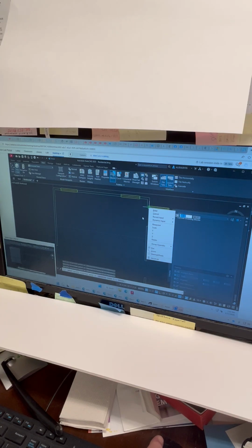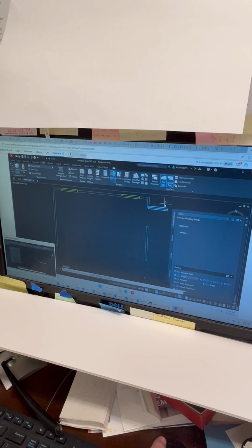Now look, auto placement, repeat placement, we've got another one. So go to the next opening. Same thing, rotation angle, except 0 as the default, just hit enter. All right, now move to the next window. This one's a vertical one. Select the midpoint,